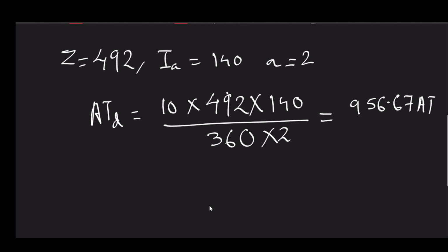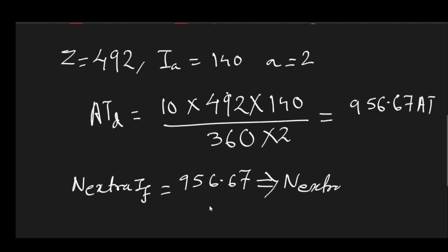Now the field winding is separately excited. Find out the number of extra field turns. So it is implied that field current remains constant at that 10 ampere. So what is the extra number of field turns? Okay. Now a fractional number of turns is not possible, so you can consider 96 turns.